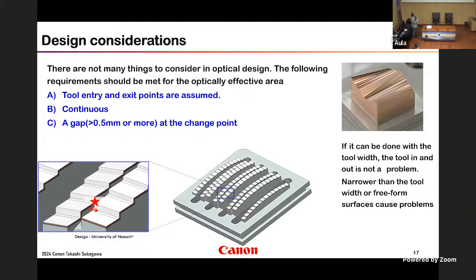What is important for the gap is that smaller is not necessarily needed, but we are very happy if the gap is 0.5 millimeter or larger. Of course, we can negotiate. That is what comes from this number. It allows us a lot of time, machining very slowly. Of course, this gap can be much smaller, 100 micron maybe possible. But anyway, nobody wants the very high cost. So we operate with the maximum speed, and 0.5 millimeter is quite enough for spacing.